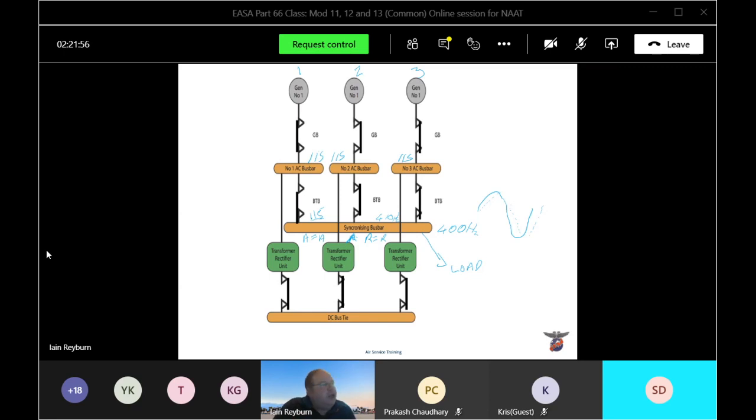Going back to the old days, we used to have a flight engineer. Looking at his gauges, he would individually open the bus tie breaker on each generator. He'd open this one, and if the fault was still there, it wasn't number 3 generator. He'd close number 3 and open number 2, and if the fault was still there, he'd close number 2. If he opened number 1 and the fault cleared, he would know that the generator causing the instability was number 1. Again, this is all done by the computer now. So that's what instability protection is.